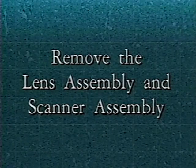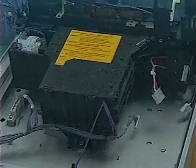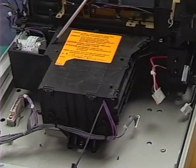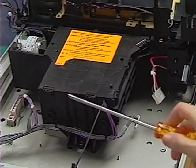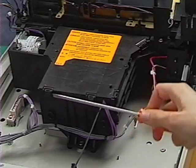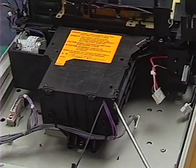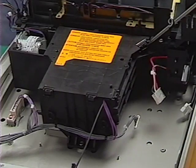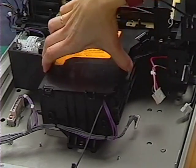Remove the lens assembly and scanner assembly. First, remove the large silver screw that holds the scanner assembly cover in place. Now unlatch the 4 cover hooks, and lift the scanner assembly cover out of the printer.